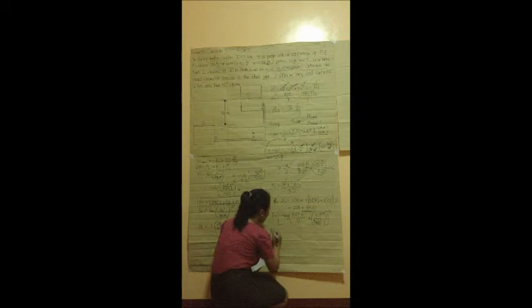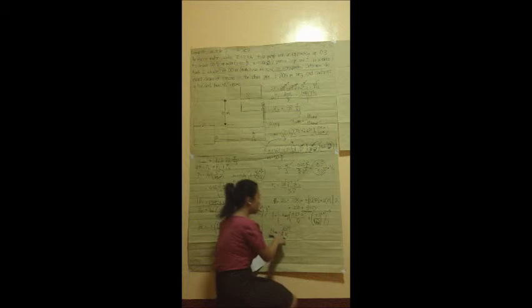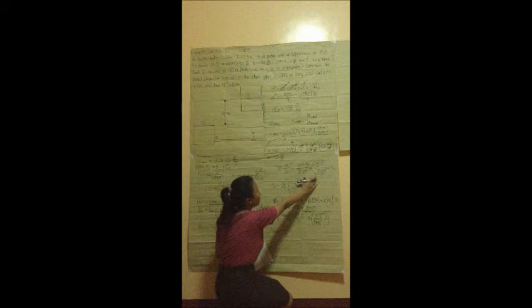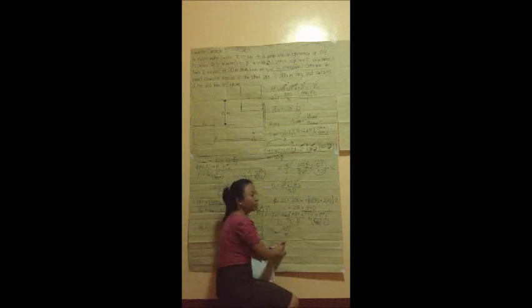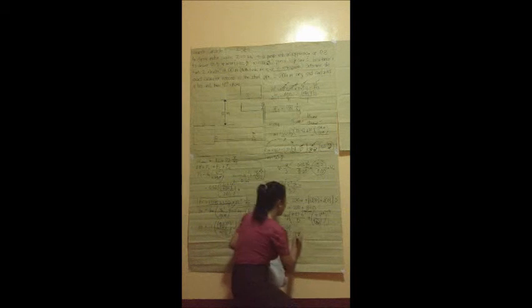The Reynolds number has the formula of dV rho over mu. D is missing, so let's leave it there as a variable. V, we have the value of velocity. Then the density is given 1,000 and the viscosity is 0.001.